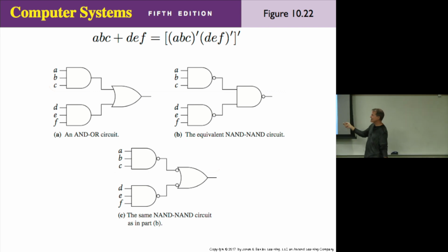So look, instead of constructing an AND OR circuit with 2 ANDs and an OR, we can just do NANDs. We replace these ANDs with a NAND, we replace that OR with a NAND, and this does the exact same thing. Now, isn't that slick? It's pretty cool because on a chip, like the 7400, you could just do a two-level circuit with one chip.